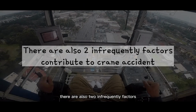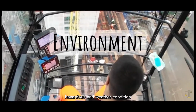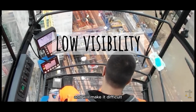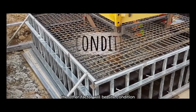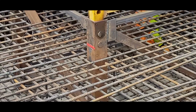There are also 2 infrequent factors that contribute to crane accidents. The first is environment. Hazardous and weather conditions can contribute to crane accidents due to the crane operator's low visibility, which makes it difficult to lift operations. The other factor is site condition, where insufficient investigation of ground condition can cause a failure of the tower crane foundation.